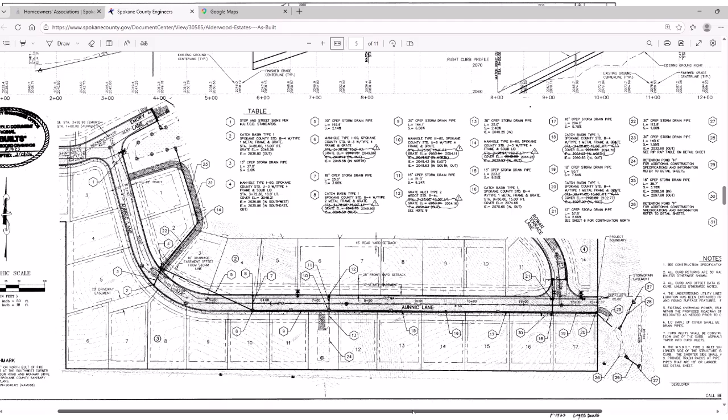You can identify stormwater features by matching the notes with the feature's location by their number. For example, number 2 is a catch basin and is shown here on the plan set right about where the road turns on the south side of the road. You can also note that there are detention ponds at item 24 and item 26.